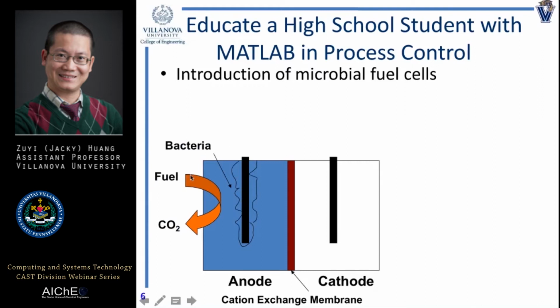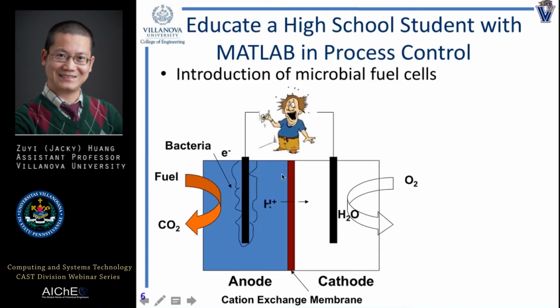For example, organic compounds from wastewater. This is a little cartoon showing you the mechanism of the microbial fuel cell. We can see that the organic compounds are converted to carbon dioxide, electrons and protons, and then the electrons travel through the external electrical circuit to the cathode, and then react with protons and oxygen to produce water.